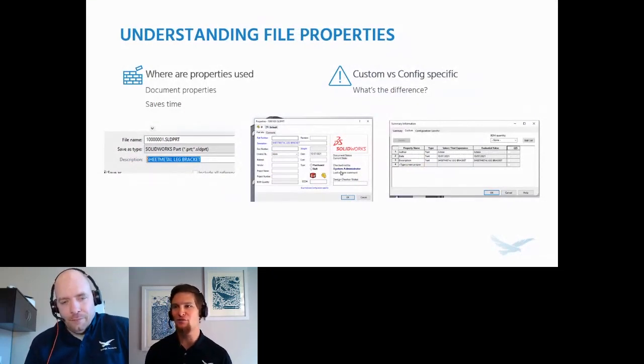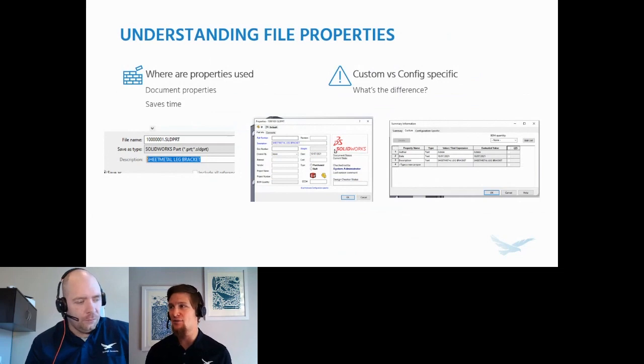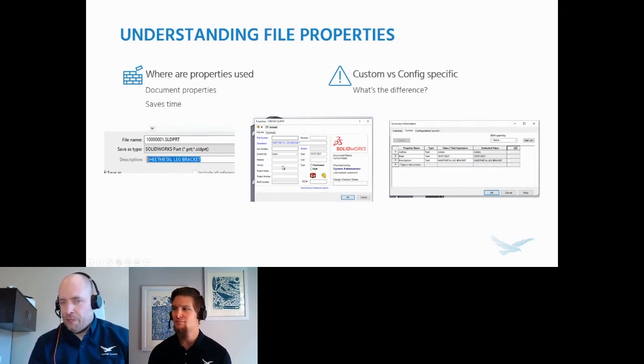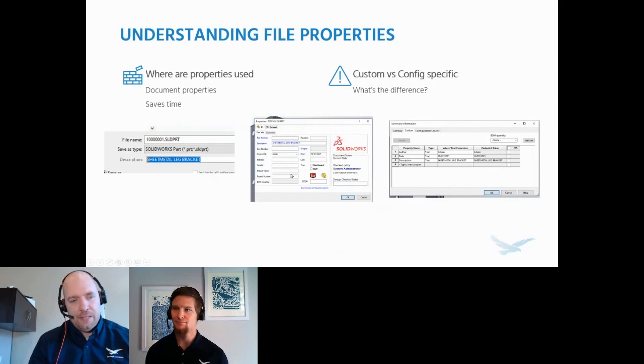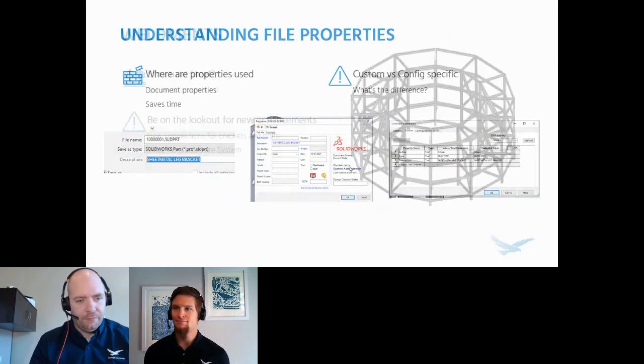I'm a big fan of using those data cards for sure, just because it makes for such a simple layout. You can really customize the information that you want to use. Yeah, and if you're not using data cards, if you're not using PDM, you could always use like the property tab builder, or you could create your own macro that shows you a form, that sort of thing. There's lots of ways to do this, but use the properties. Don't put the description or revision, that stuff inside of your file name. You'll be a lot better off. Good advice.